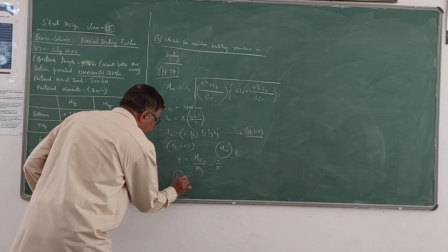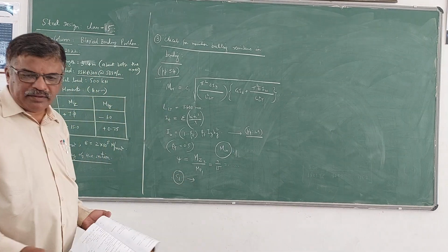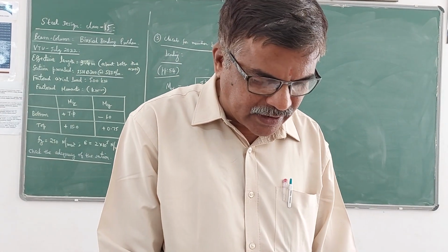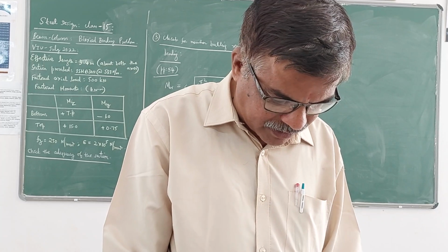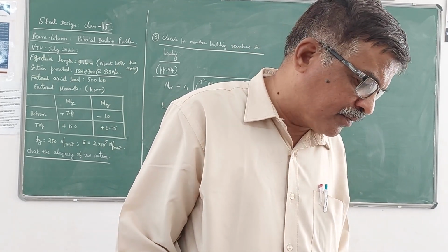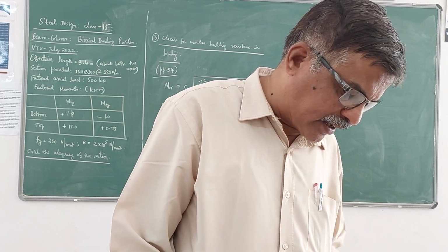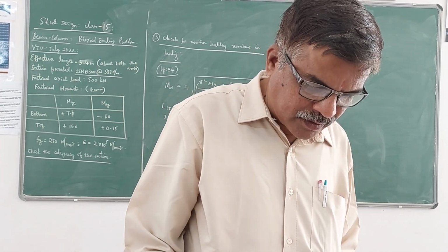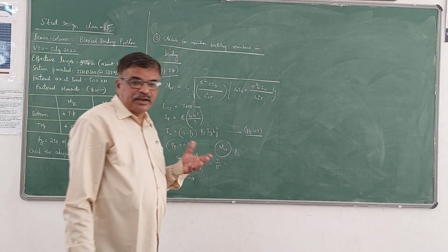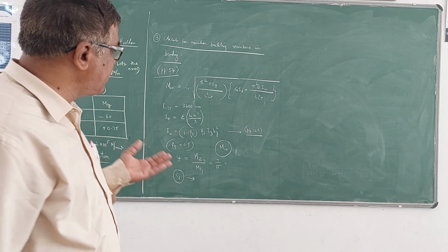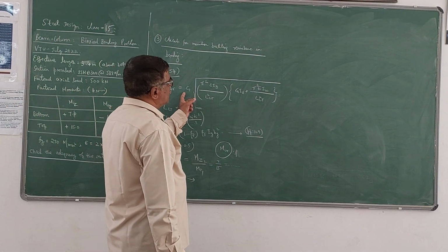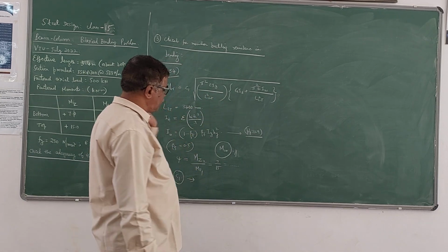Of course, these things I have explained in the procedure. The C1 value you can get from page number 72 in the code, you can refer to that. This beam column example is from pages 70, 71 and 72 of the code. Once you get this C1 value, substitute all the values here and get the value of MCR.